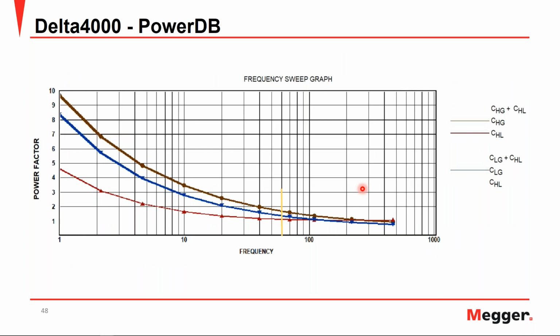If we scroll down from there, we can see a window like this that shows the actual narrowband dielectric frequency responses being highlighted and shown graphically. And you can see again from 500 to our 1 Hertz, we have our 60 Hertz value here. And as the sensitivity towards the lower frequencies increases, we have our higher power factor at our 1 Hertz measurement.